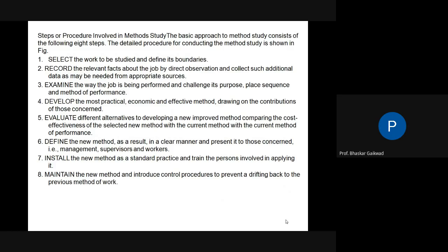That is the gear blank. So first you can study the drawing, then you can make the program as per the dimensions. Study the geometrical and dimensional tolerance. After this, you can make the program and feed this program into the machines.